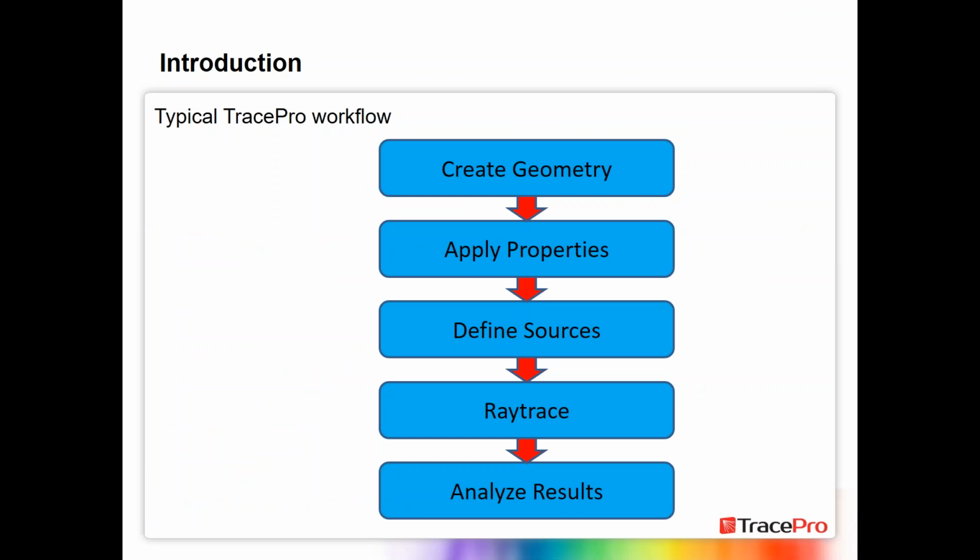So this is the typical workflow in TracePro. Create the geometry, apply properties, define sources, run the ray trace, and analyze the results. And you can do all of this right in TracePro itself.